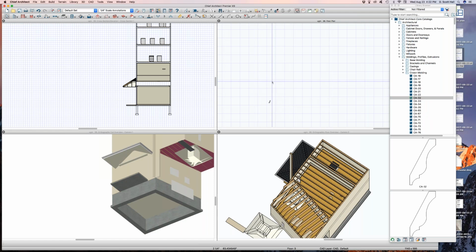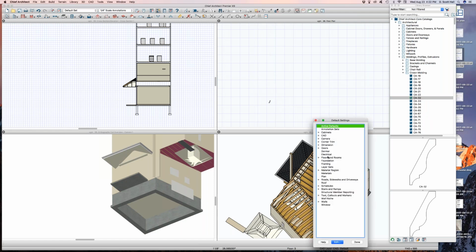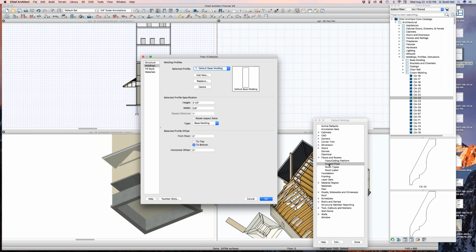It is. Here's something I tried that you guys might be interested in. I used the base moldings to put perimeter foundation drains in. Excellent. Oh, yeah. Say that. And I used piping and changed the size of the piping to 6-inch. I missed your first statement. Can you say that one more time?